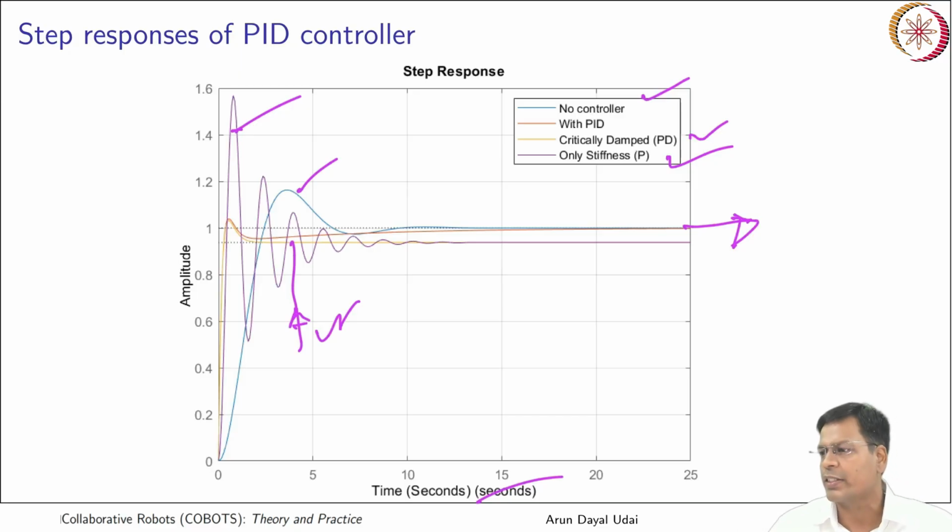Okay, so now you saw it was very difficult selecting the gain. You understood where the problem is. Okay, you saw the state of your system, you improved upon your p value and I value, d value, all the gains you have adjusted. But you see, it is very much based on your experience, your trials. So this is one of the biggest challenges even now when you have to select the gains, even for a single input and single output system. So forget about multiple input, multiple output, coupled systems, higher order systems. So it is really very difficult.